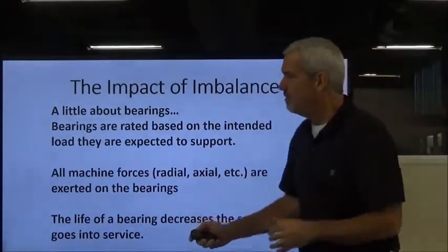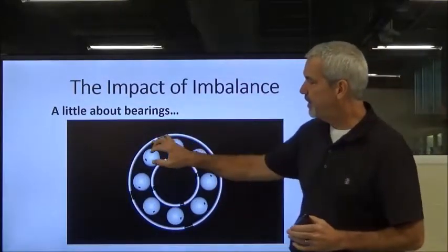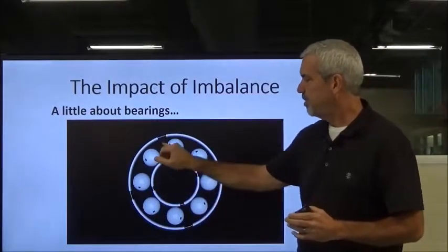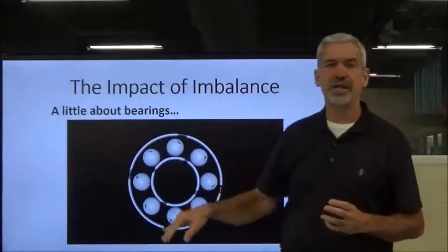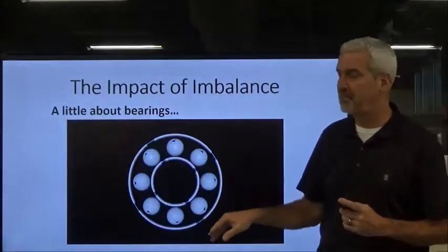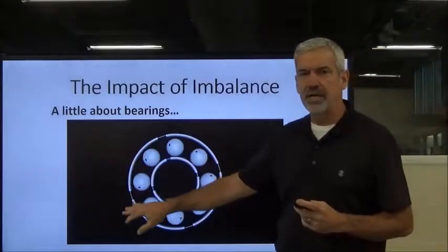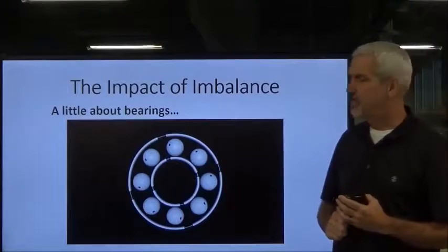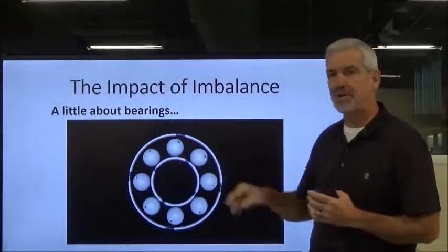But anyway, moving forward, this is the bearing. I showed you here, this graphic here. This is the outer race, the inner race, and the balls that go in there. Okay, and each one of these vibrates at a different frequency. Now, in later lectures we're going to dive a little deeper into this, but the bearing can give you different frequencies. One bearing can give you multiple frequencies coming out of there. The frequency of the inner race and the outer race and the ball, they're all different.